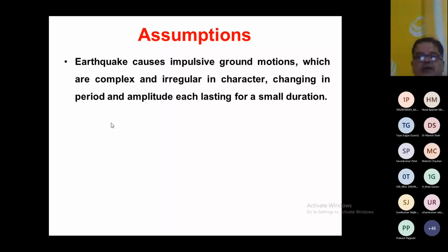Now they concluded that this was a very low frequency earthquake, and throughout the shaking the frequency did not vary much. It was not changing between 3 hertz and 20 hertz; the frequency content of the earthquake was in a small, narrow range.